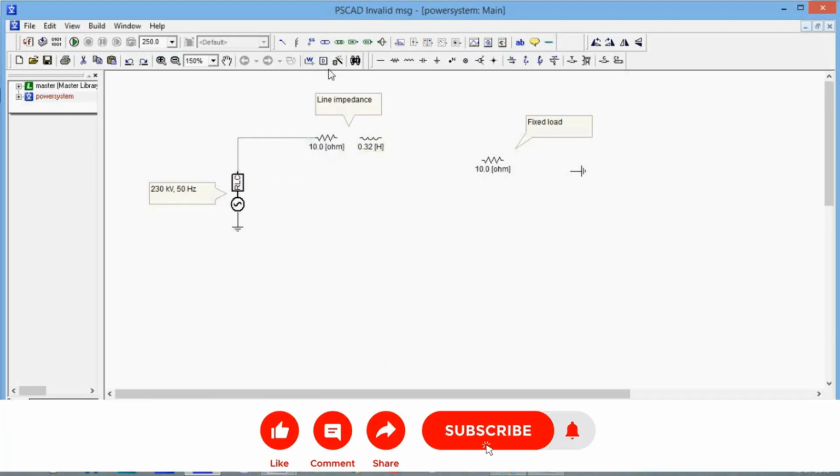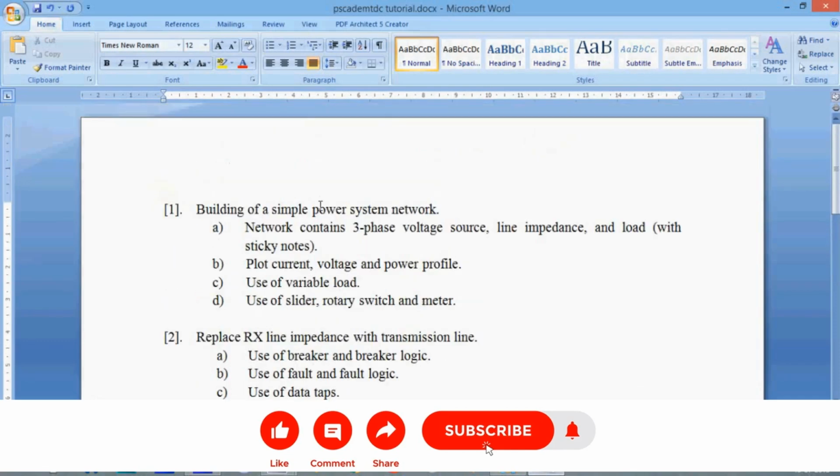Then next click on the wire, join this, escape. Click here, here, here, escape, and here, here, here, escape. So this is our primary model of a basic power system containing a three-phase voltage source, line impedance and load.